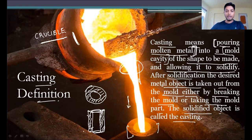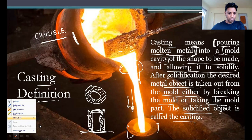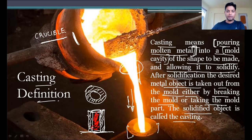In between we are keeping it on the molding sand only. We are pouring this molten material into this one, so it will be completely filled, okay. And once it is completely filled, we keep it up to the solidification time. Solidifying is not a different process; we are just keeping it for some time in a place where atmospheric gases should not react with it, otherwise it will form oxide.